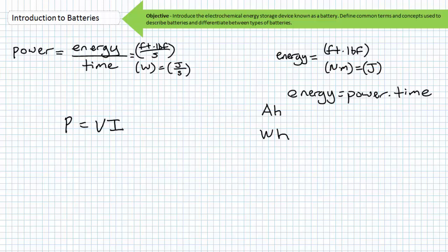Returning to our discussion of the amp hour, electrical power is the product of voltage and current. P equals V times I. Units of watts equals units of volts times units of amps. The energy unit amp hour assumes a user is comparing batteries with comparable voltages. What is missing when expressing the energy capacity of a battery in amp hours is the nominal voltage of the battery. Energy is power times time. Power is voltage times current. Energy is voltage times current times time. Amp hours is only 2/3 of the picture.